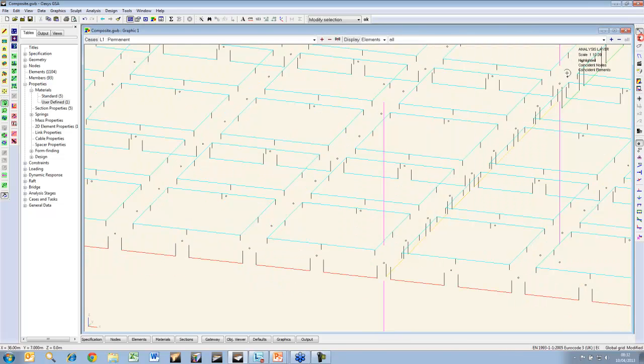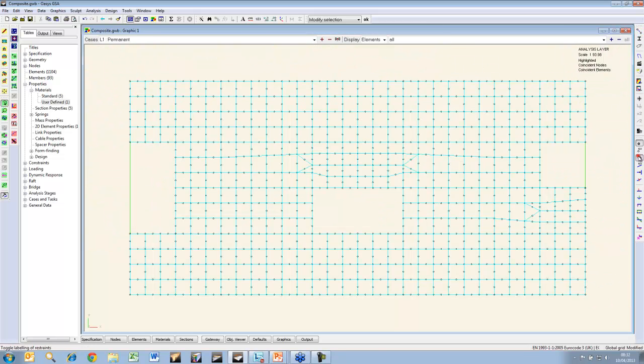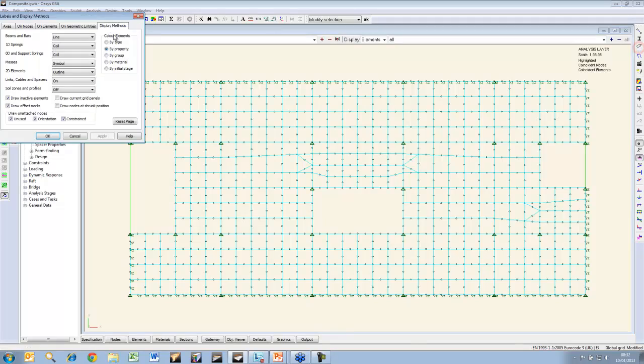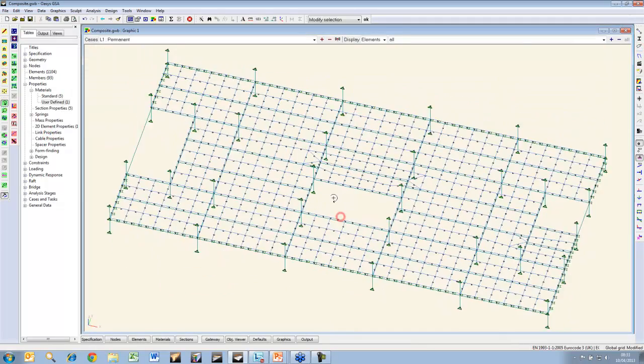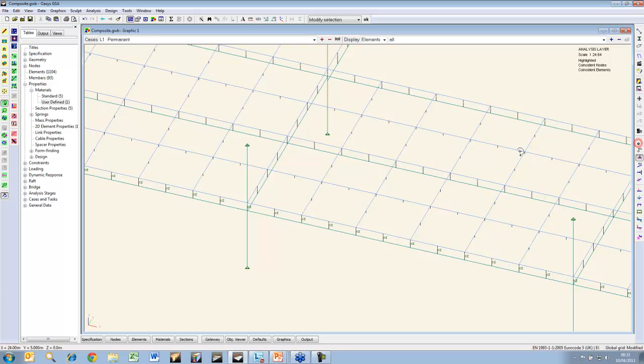Now, what else have we got in here which is different? Let's look at restraints. Now, let me switch the colours off as well. So you can see that with model as a subframe, I've got pin supports on these half-height columns. So I've only modelled columns halfway to the next floor. I've also got restraints around the edge nodes. So you can see I've restrained all these edge nodes with cladding liners in the vertical direction, the Z direction, but also in the plane.